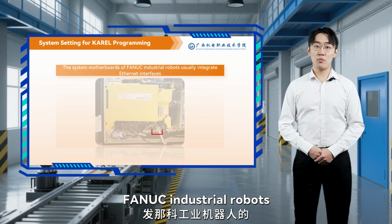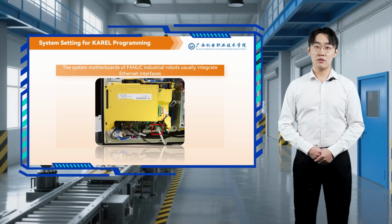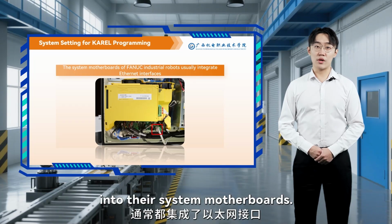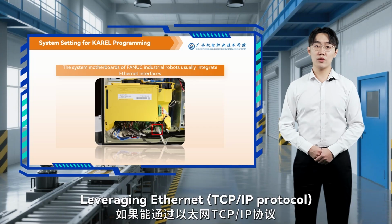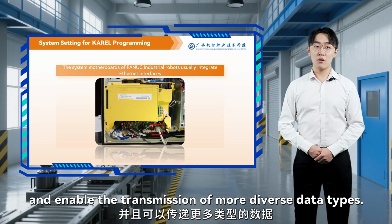FANUC industrial robots typically have an Ethernet interface integrated into their system motherboards. Leveraging the Ethernet TCP/IP protocol for communication with PLCs can save numerous I/O ports and enable the transmission of more device data types.